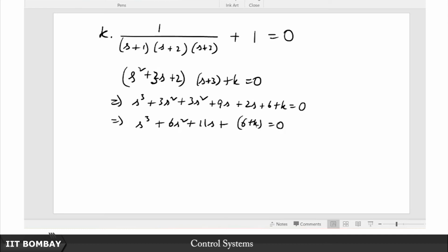I just discussed one such example as a closing statement to Routh array as an application of it. Now suppose I want to find out what is the bound on this K for stability. I might eventually conclude that for all values of K it is going to be closed loop stable, but that aside, if I do manage to find a critical value of K at which this crossover happens, then at that critical value of K, if I plug in this K crit here, what is it going to tell me? It is going to also tell me what the closed loop poles are, the solution of that equation.